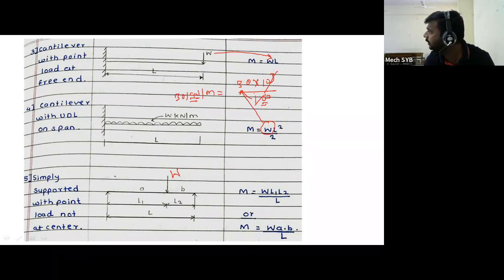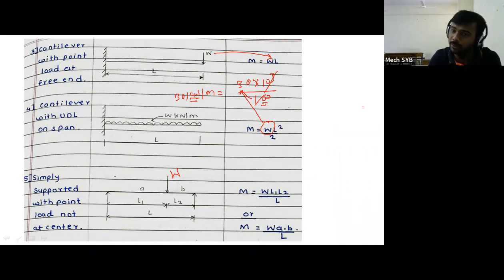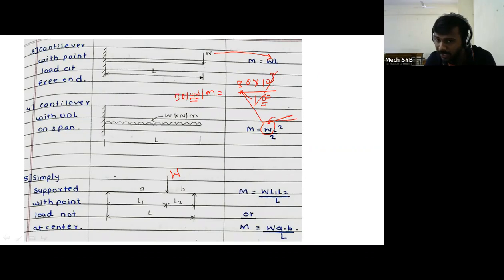Understood? Getting? That's why I have given that statement. It is very important. Many times students convert that UDL into point load and put that point load value here. Then if your M is wrong, all your further calculation will be wrong.